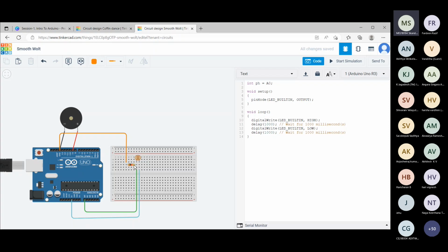This is being done to complete the circuit. The resistor here is a special type of resistor, which I'll be talking about later in the session, that is being used to initialize the value of the photoresistor to a particular value rather than allowing it to take any value at random between ground and 5V.